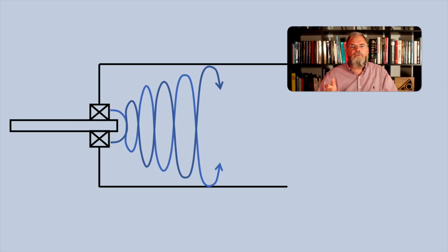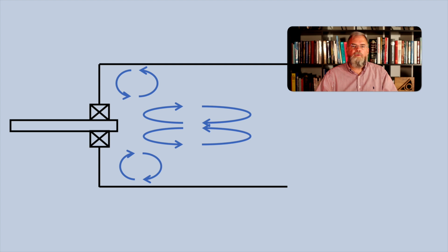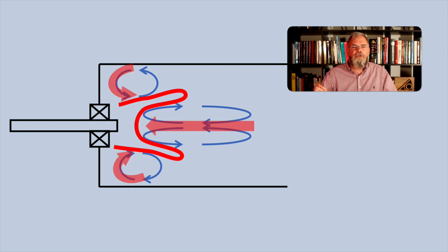The aerodynamics of most premixed burners is very similar to diffusion burners. As was discussed in detail in part 1, the airflow is introduced swirling, producing two main regions of recirculation. One at the axis of the burner due to the vortex breakdown, and one at the sides of the burner due to the sudden expansion as the flow enters the combustion chamber. As the fuel and air are premixed, there is a burnable mixture everywhere in the combustor, and so the flame starts in the shear layer of these two recirculation zones.